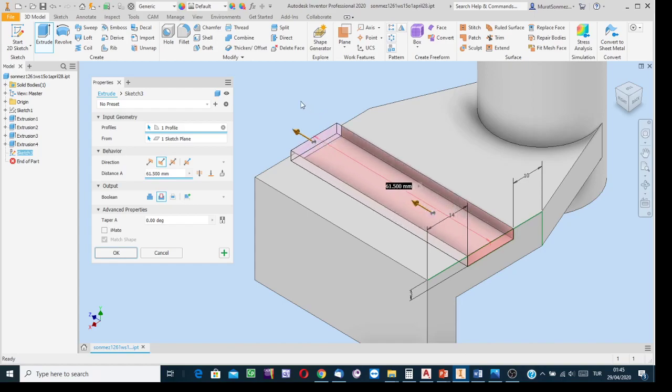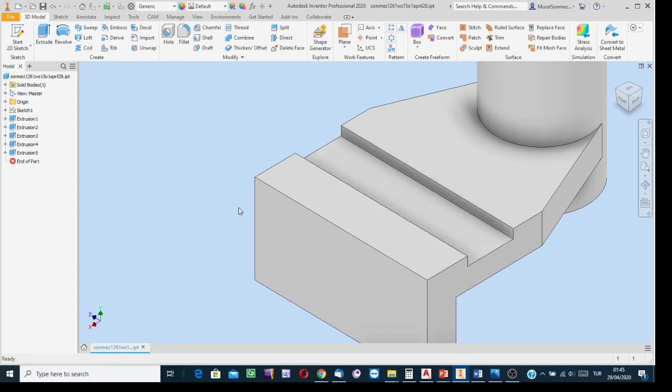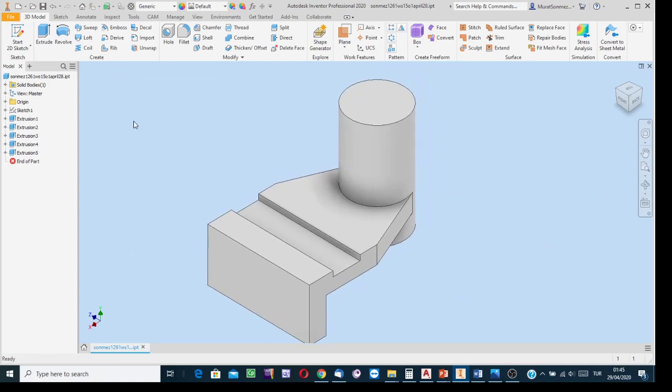Cut, cut, cut, cut, and then reach the atmosphere. Or, since it is a truly through cut, from here select the Through All button. Okay, and then say okay. Here is the channel created. Save the file one more time, and then continue.